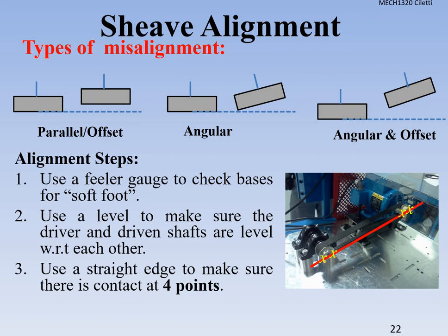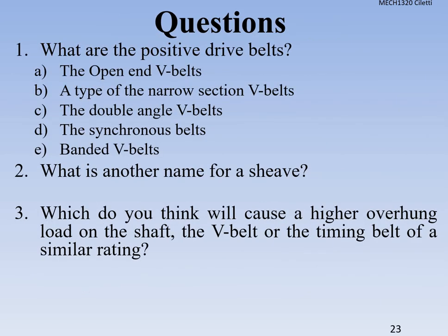Then you're going to put the set screws on. All right, so use the straight edge to make sure everything's aligned, then put the set screws on. You're going to do that in your lab, and it'll guide you through that again as well. Just wanted to make sure that I briefed you on that as we were going through.